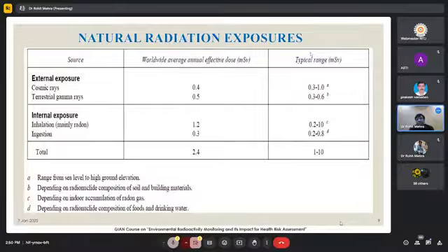The reason is that the quality and grading of fly ash is different from different thermal power plants. So we collected samples from different thermal power plants, and we found that the same ratio gives different results. That leads to further studies, that the type of coal being used in those thermal power plants is also responsible, because fly ash is only the residue of the coal.